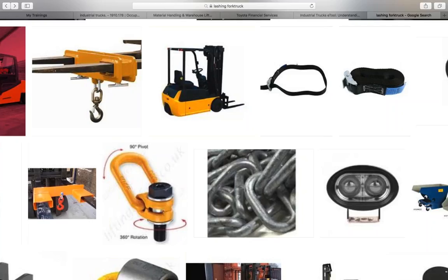Then we go into special care needs when we're doing elevated loads as well. Some forklifts have their own leveling device, so we want to take all considerations, especially with newer forklifts, which have a lot more technology now. For anybody who's wondering, we're still on page 17, upper right. It's just a lot of bullet points that we're covering. Then, of course, one of the biggest safety hazards in elevated load placement is poor visibility. We need to make sure that we can see with the load. If we can't see with the load, what's going to happen?